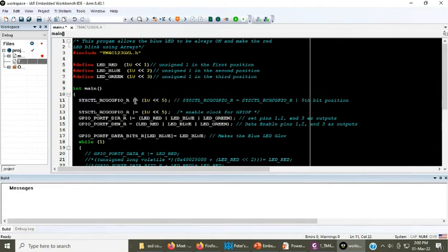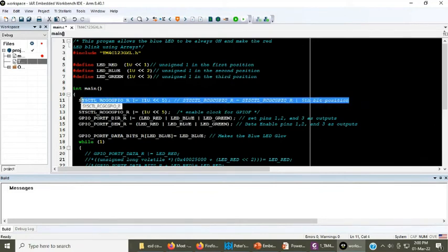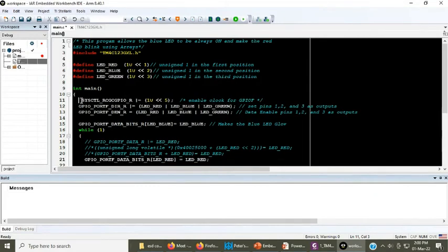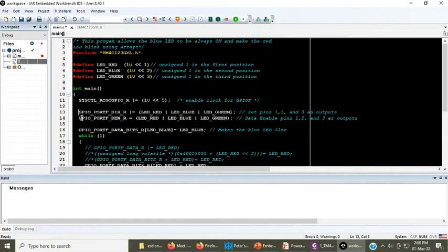So using bitwise ORing, you can just make one of the bits high or low. So this is how you are making that particular bit high. So this command will generate clock in the port F. Anyone having any difficulty to get to this point? No, sir.